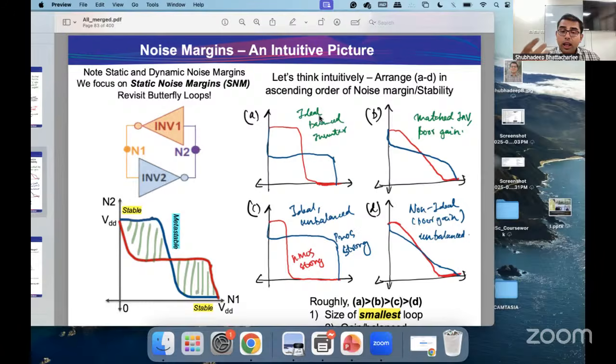But as we have shown over here, you are asking the same question in a different terminology. If the NMOS is stronger or a PMOS is stronger, your inverter balance will just tilt away. For example, here, if the NMOS is stronger, the red line will be the transition in the VTC characteristic. If the PMOS is stronger, it will be something else.